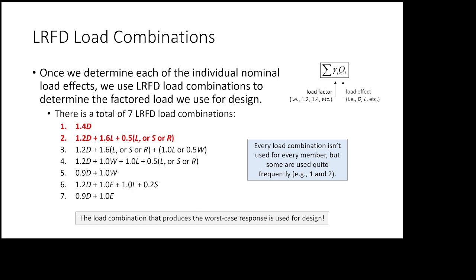But it's like, for example, load combo 2 is more or less reflective of a general purpose use of the structure. Load combo 1 is probably more representative of a load combo that was controlled during construction because there's no live load. When in the life of a building is there no occupancy load? When it's being constructed, because there's no people in the building because the building ain't finished yet, right? So that's kind of the idea there, although we still need to check all of them and whatnot.